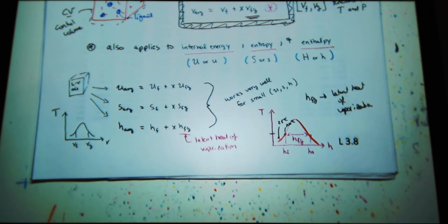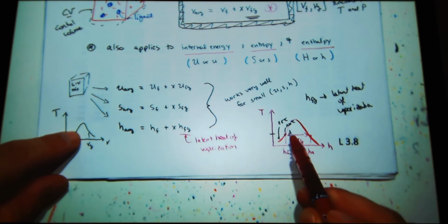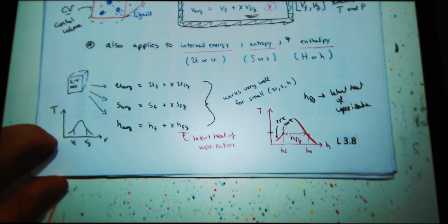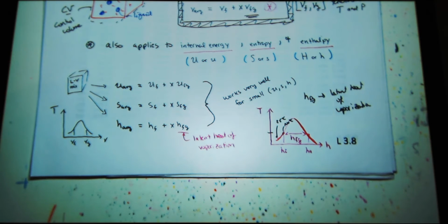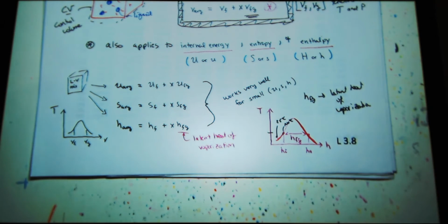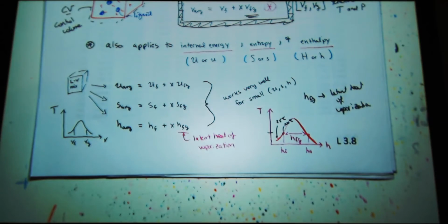So if you knew how much power was coming out and the energy you put in, you could calculate the energy consumed, and so then you would get some value for energy, and from that you would know where on this curve you were. I'm just pointing out, though, if I tell you the vapor quality is 1, or if I tell you the vapor quality is 0, and you're dealing with liquid vapor mixtures, you should always get an idea about drawing a curve like this.